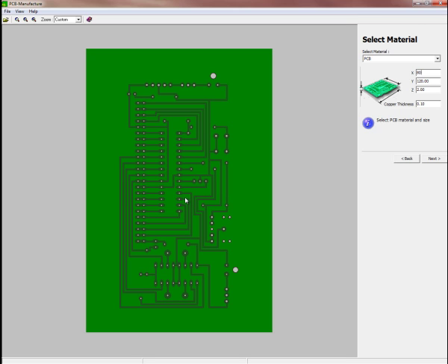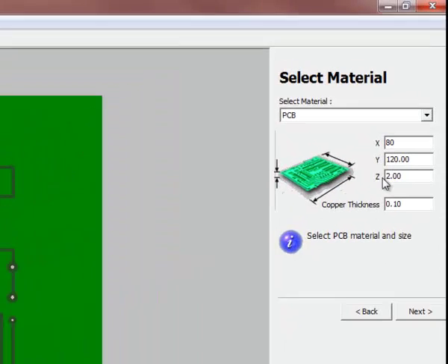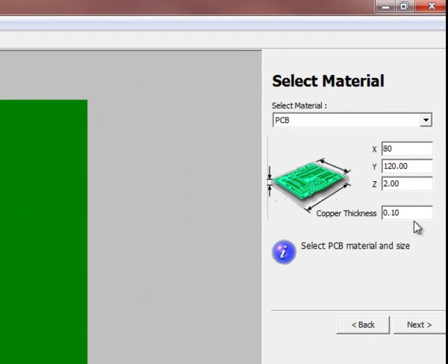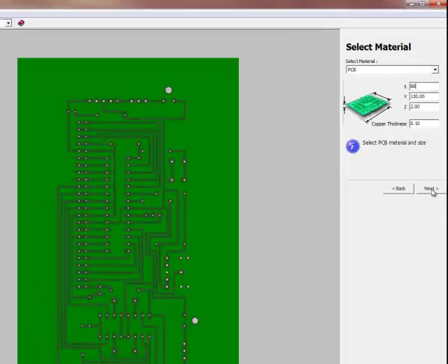It's handy for clamping, it's also handy for any additional screw holes that you may want to put in to help secure the board. Most of the rest of the settings I have are quite fine. 2mm thickness overall, and then 0.1 for machining is normally about right for most manufacturers. That's about the thickness of the copper that they use.